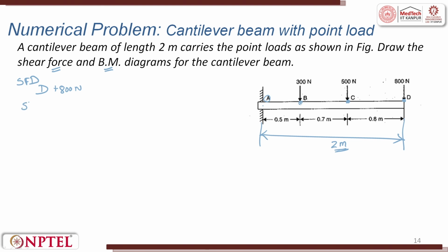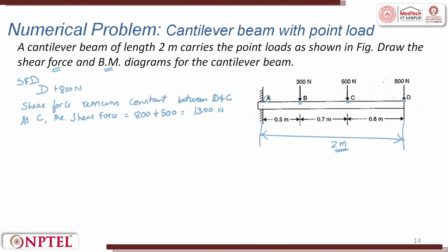The shear force remains constant between D and C. At C, the shear force is 800 plus 500, which is 1300 Newtons.